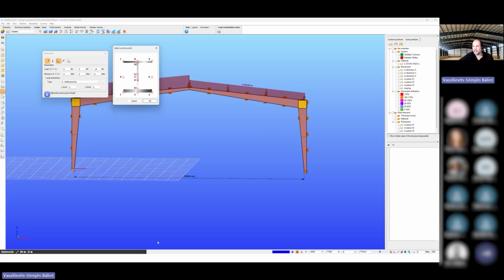If you are ready and you want to have correct documentation and prove that you checked everything, then it's well enough to create categories of load combinations and select the left-to-right type of combinations and separate them from the right-to-left. And yes, at the moment, you will need to have 2 different imperfections. In the worst case, 2 different models, one saved with the positive values of imperfection, the other saved with the negative values of imperfection.